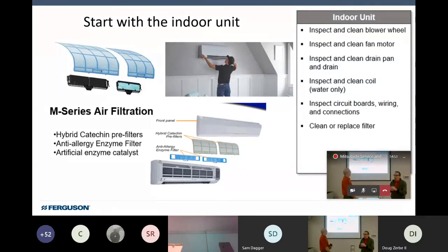Yeah. So we're going over the filters. We're going over cleaning coils. And yes, so mild detergent, but make sure you get a good rinsing of that. Because like I said, if you think about how narrow those aluminum plates are on the copper tubes, the water is supposed to follow that plate down. If it comes down and hits a gap that's filled, then that water droplet comes out to the face of the coil.